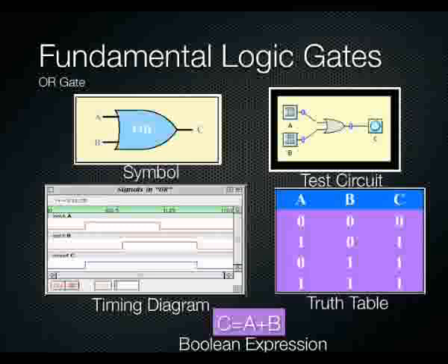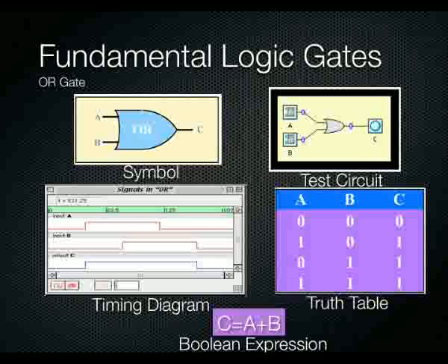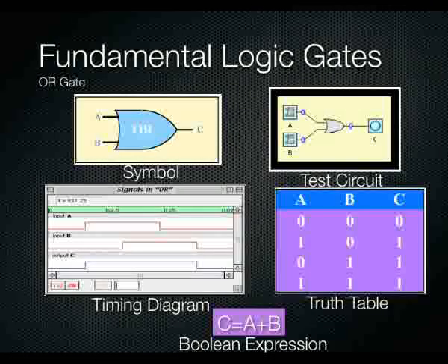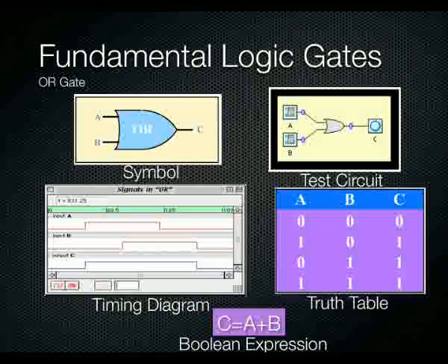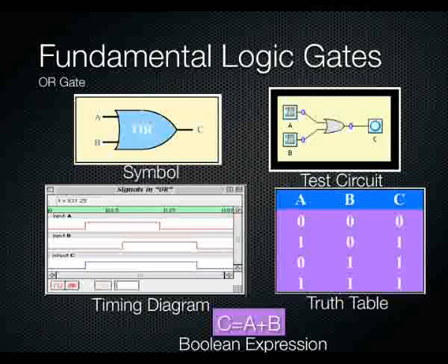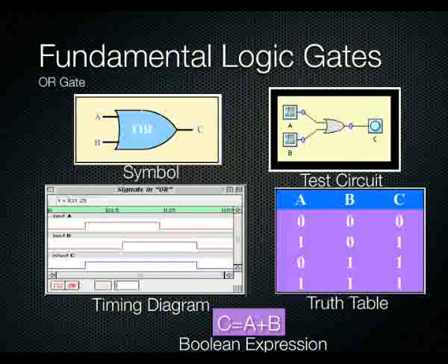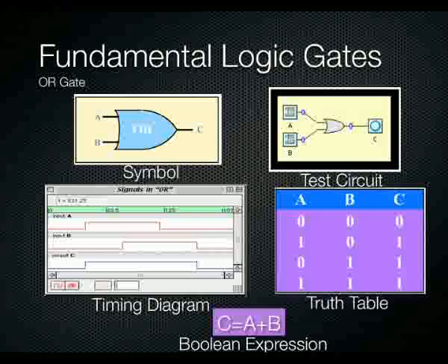Like the name suggests, it's digital logic, and the word logic implies that we're doing logical functions. Therefore there exists a series of gates to provide the basic logical functions. Of course, the most primary of any logical functions are the OR and the AND functions. So we have a gate to provide the OR function. When any of the inputs is 1, the output is 1 also. And if both inputs are 1, then the output is 1 as well.